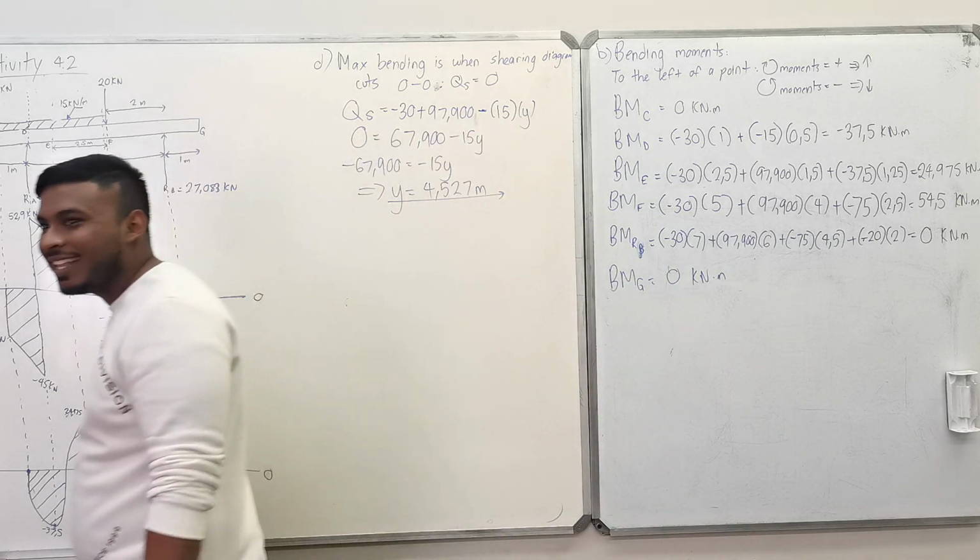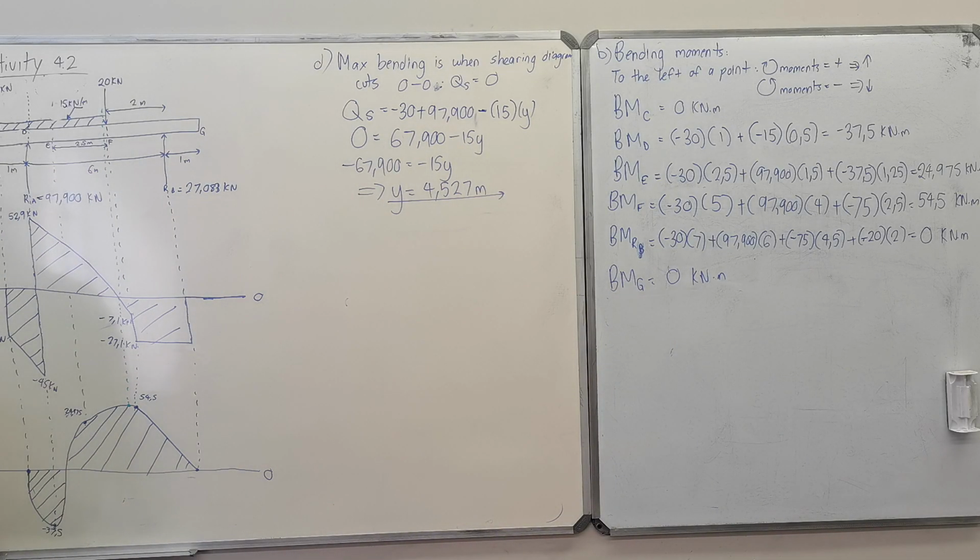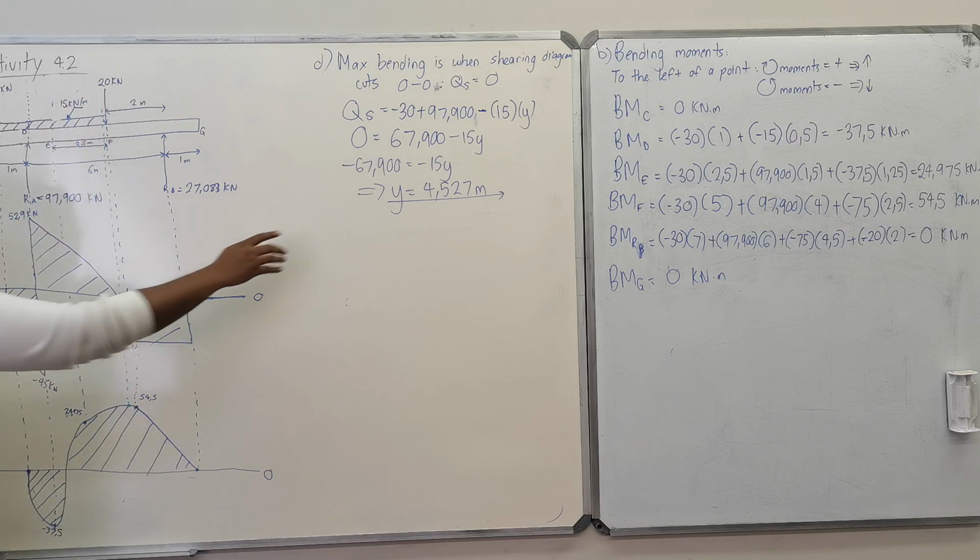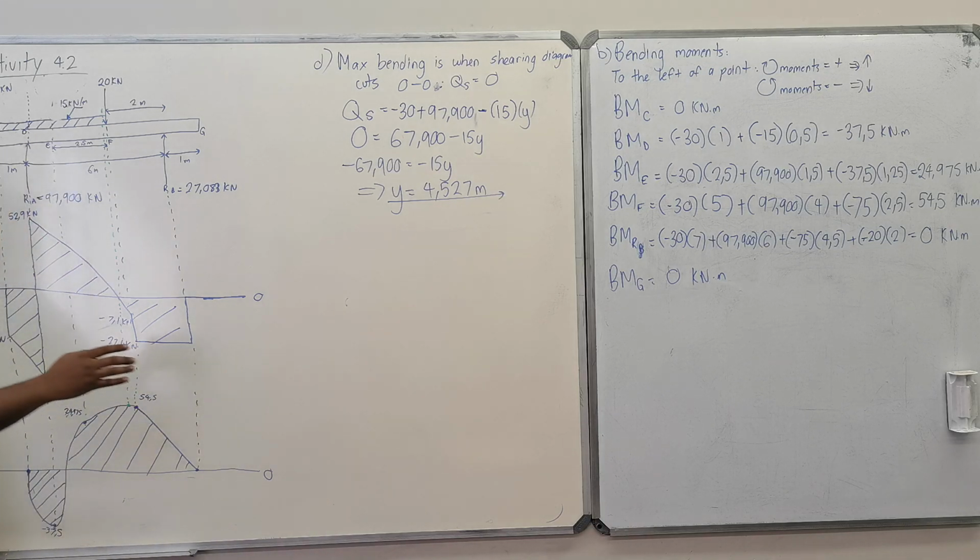You work the forces times the distance on the left hand side, exactly like how you would solve for a bending moment. So remember this green line, guys. Please don't say it's at the end where the 20 kilonewtons is. That's a mistake. It's 4.5 meters, 0.5 meters away from the end. So there's no way you could have used anything from there to work it out. You have to use your shearing force equal to 0. You work out that distance, now we've got the position.